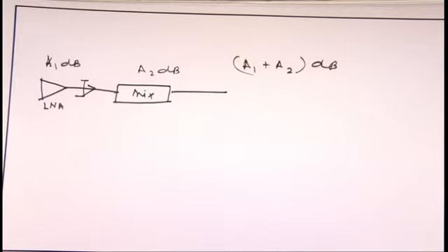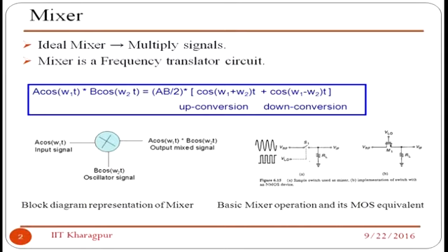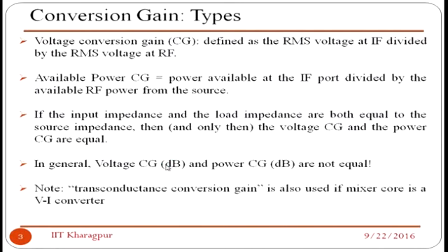So that is some of the implementation tricks I should be able to percolate. What I am saying is that it is basically the multiplication of two sinusoidal signals, A cos omega 1 t and B cos omega 2 t. One is essentially the switching and the other one is the modulating. So that is a kind of mixing, and you have the up conversion and the down conversion.